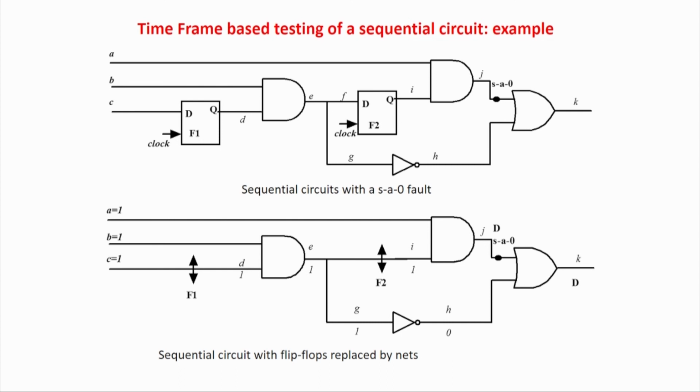It only reduces the test pattern generation time, but that is a secondary factor because test patterns are generated only once at the software level and they have to be applied to all the circuits. So, test pattern application time is very, very important compared to test pattern generation time. But on the other hand, if your circuit is very, very large, you would also like to optimize at the level of test pattern generation.